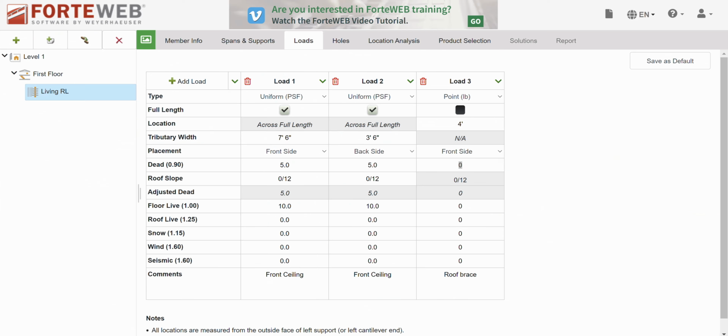Now my roof weight, dead load, is 10 pounds per square foot. So I'm going to take that number, multiply by 10, 440. And I'm going to take my roof live load, and it's 20. Now 20 is just double 10, so I'm just going to double my number. Now I'm going to go back to my dead load.